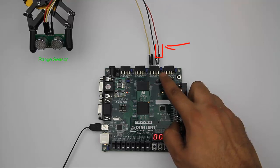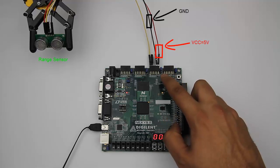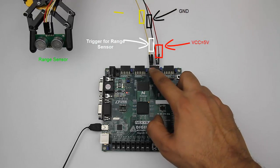The 4 wires that are connecting the range sensor to the FPGA are a 5-volt power supply, a ground, a trigger for the range sensor, and a pulse from the range sensor.